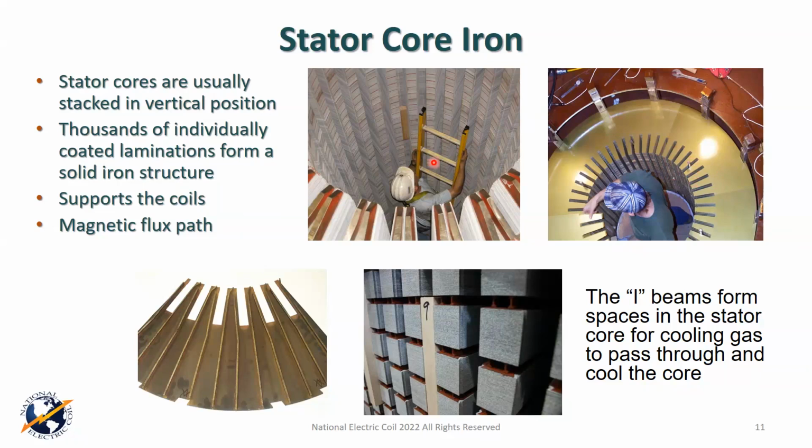Now, we talked about cooling and the importance of cooling. So you got areas where that cooling gas can go in a lot of machines. Not all machines have them, but most of the machines have cooling vents in areas, okay? And where you have those cooling vents, you got to create that path for that cooling gas, and that's what this vent plate is that you see over here. This is a little bit of an unusual one. It's got the notches here on the back instead of a traditional key bar or a building bolt.